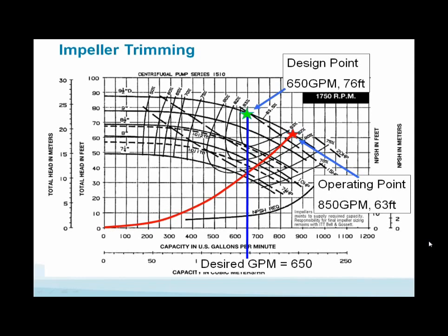What are you saying, Chris? I'm saying to you that the brake horsepower has dropped. We've gone from a 9.5-inch impeller, not a half-inch impeller, down to what looks like about maybe 7.5 roughly, and the brake horsepower is probably going to be 7.5 to 8 horsepower. So we cut the operating cost significantly.